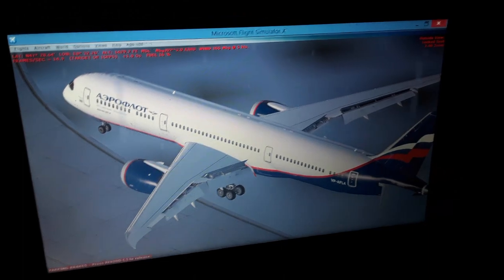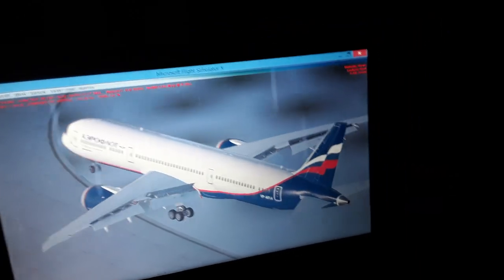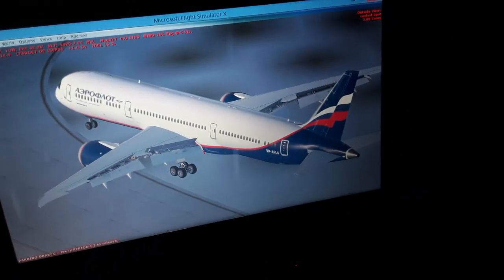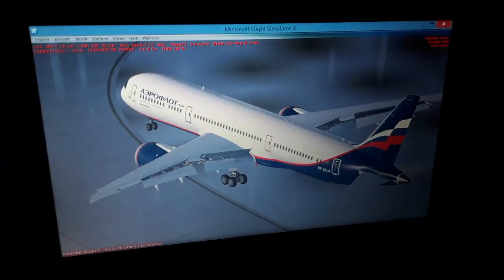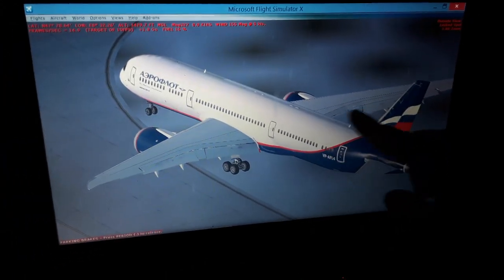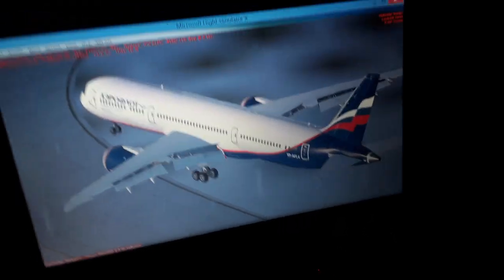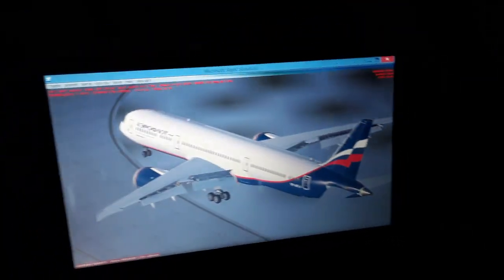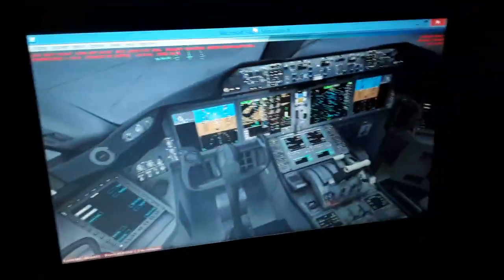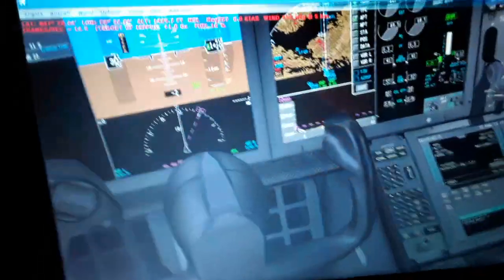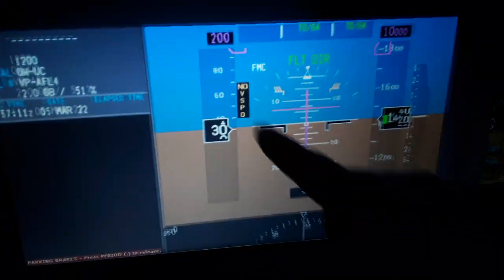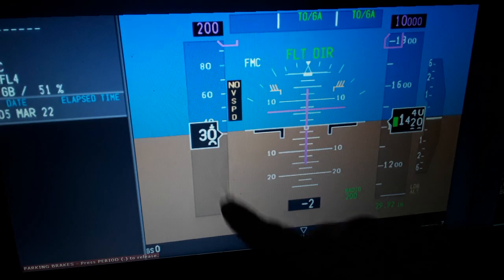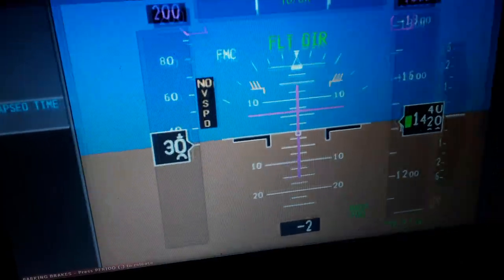The airflow becomes detached as we fly. Also the center of pressure is moving back and forth over the top surface of the wings. So when we have the stall over here, we need to monitor inside the aircraft. You see the primary flight display, you can see the airspeed indicated over here, and we have also the stall speed indicated. You can see the airspeed tape, and the stall speed with a red and amber yellow indication over here.